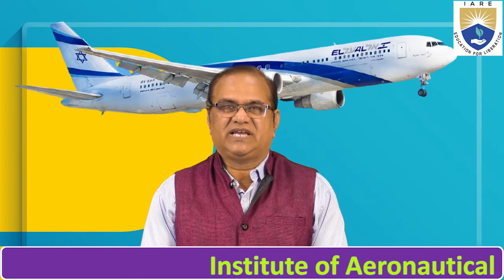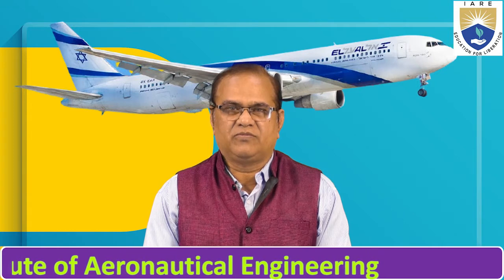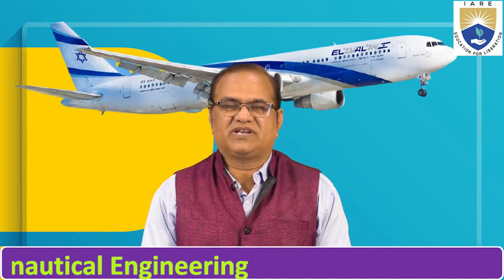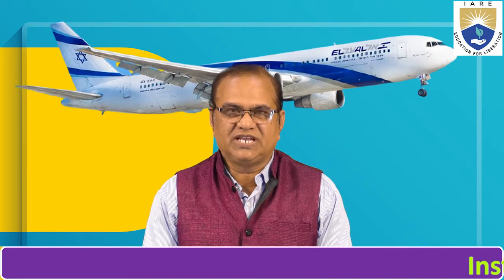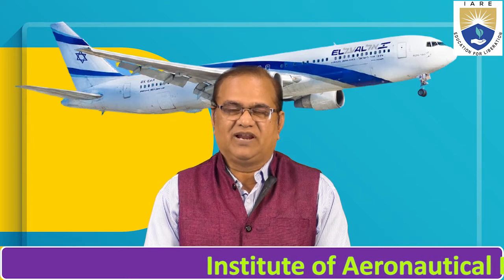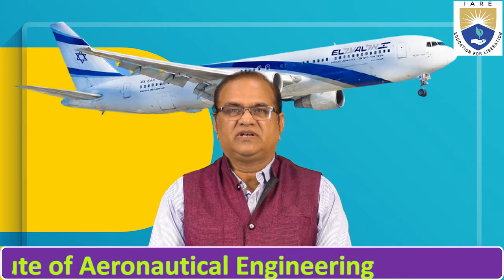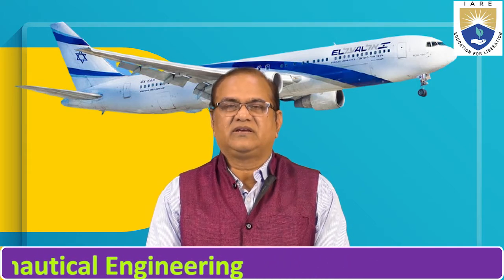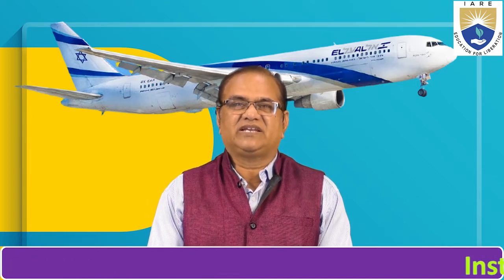Out of these six, there are four in which static stability persists, and out of these four, only two motions, the damped oscillation and the subsidence, are dynamically stable also. So to have dynamic stability, the system should first be statically stable. However, static stability doesn't mean it should be dynamically stable.